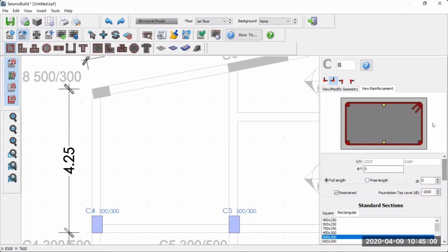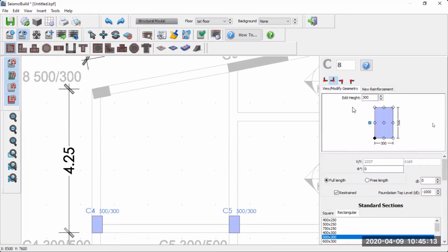All right. The way we're going to do the insertion point is, you notice that this column is inclined. So we're going to change our orientation to this corner. All right, and then we put our insertion point here in this angle. The angle will be based on the rotation point. In this case, I already worked out the angle is about 11 degrees. So I type 11 degrees. So you can see that it is already rotated by 11 degrees.